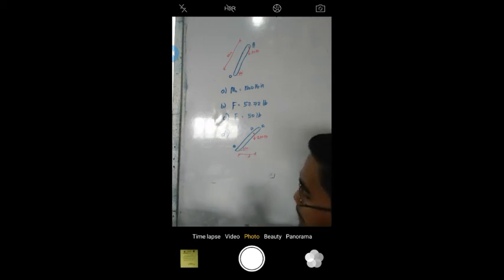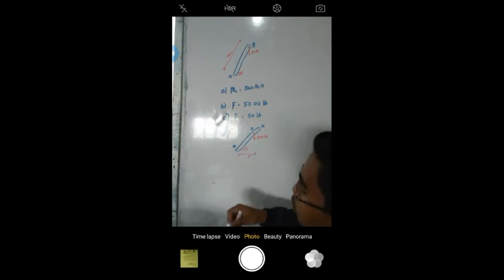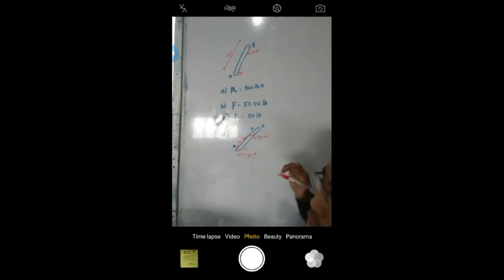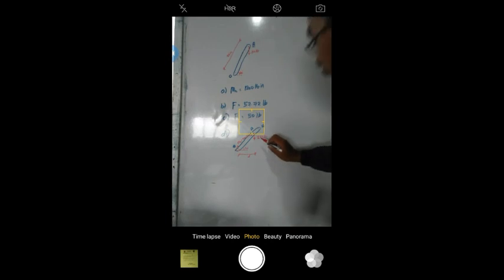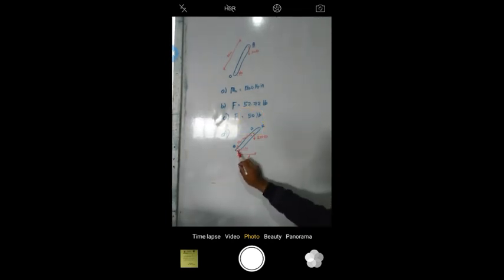So the 240-pound vertical force with respect to point O must create the same moment. Again, the moment is the same, which is 1,200 pounds-inch. We want the distance of the 240 pounds from point O that creates the same moment.